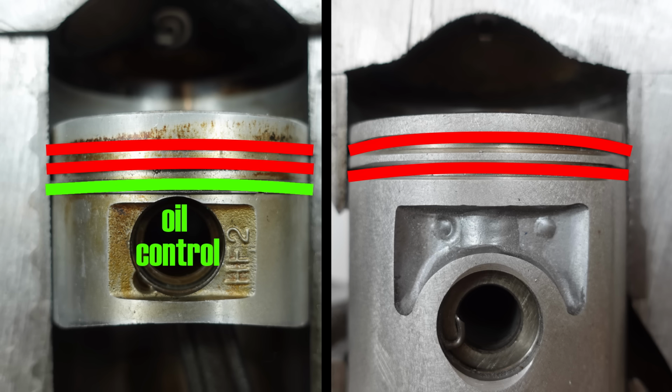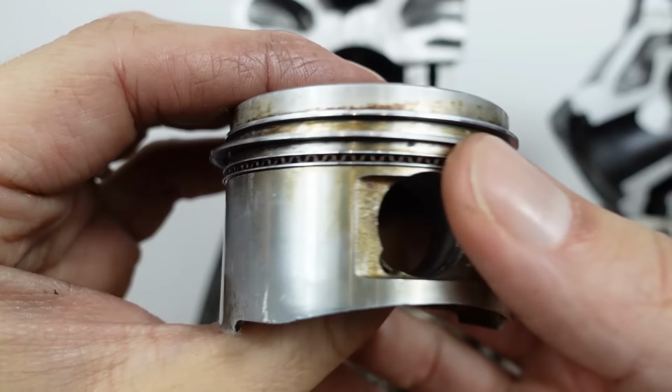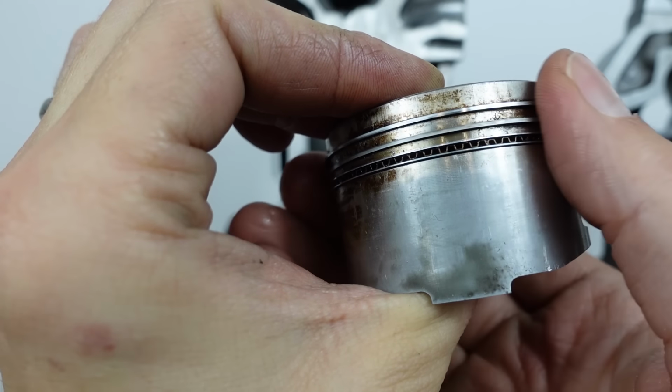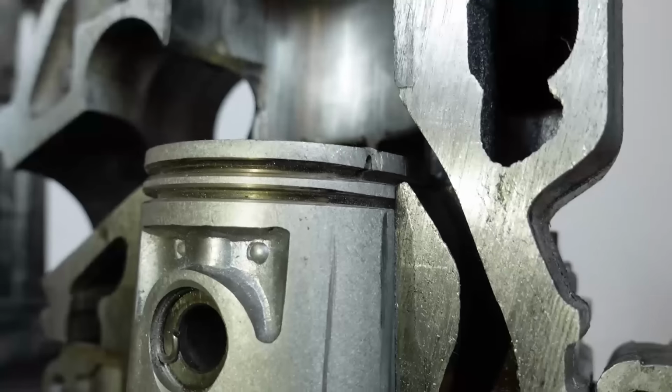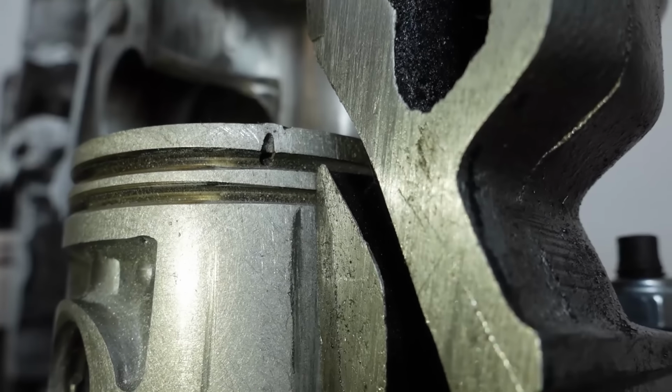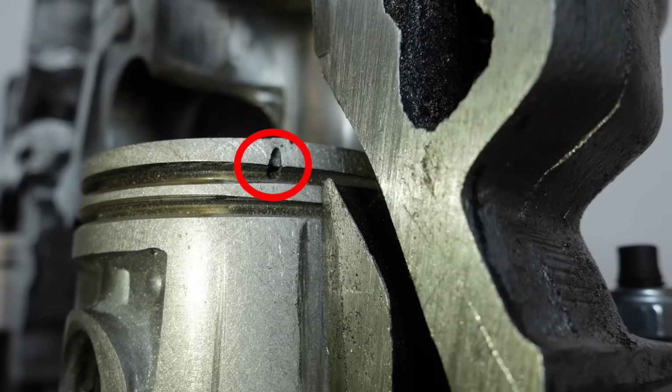But there's a benefit for the 2-stroke here because less rings means less friction and less power losses due to this friction. But the piston rings don't just differ in number. They're free-floating, or allowed to rotate, in the 4-stroke, whereas in the 2-stroke they are pinned in place using small pegs. Now these pegs are missing from this particular piston, but you can still see the holes where the little pegs or locating pins go. Their purpose is to prevent 2-stroke piston rings from rotating.